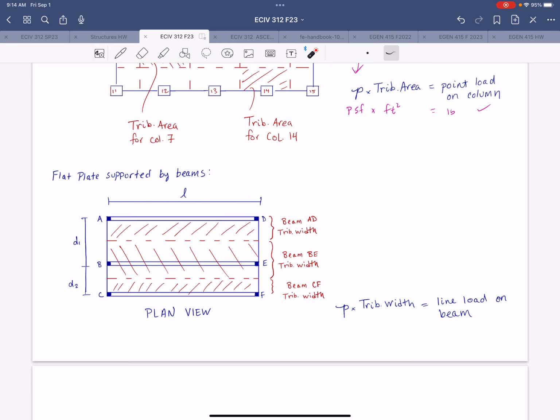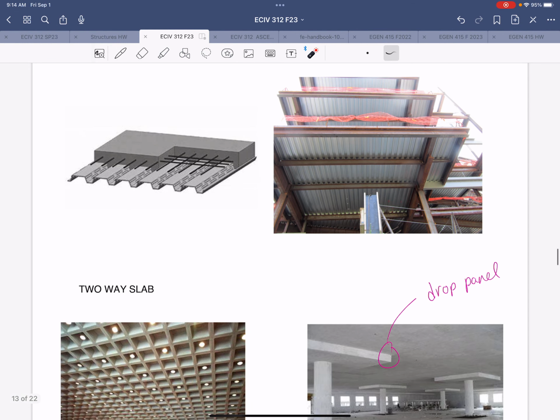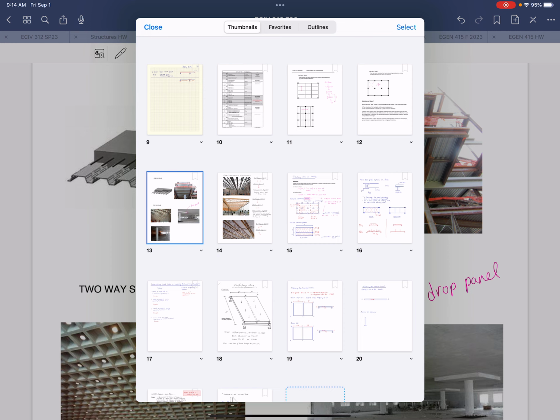Also, if you have a floor surface that's something like this, where you've got the corrugated metal decking that can really only transfer load in one direction, then it has to be a one-way floor system, regardless of what that ratio is, all right? So use that ratio with a grain of salt. It's not always going to give you the answer.